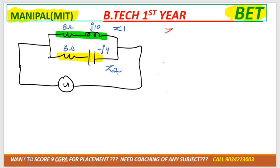So how can we write this down? Z1 is equal to 8 and 10. As I told you earlier, if RL is the load, then in that case the Z formula is R plus JXL. And what is R over here? 8. And what is XL over here? J10. So 8 plus J10 is your Z1 value. Similarly, tell me what would be the value for Z2 in this case?